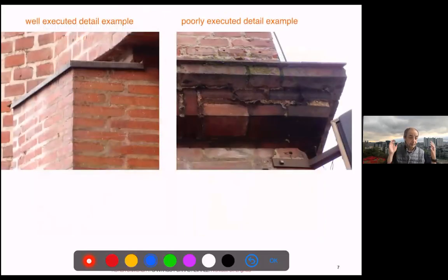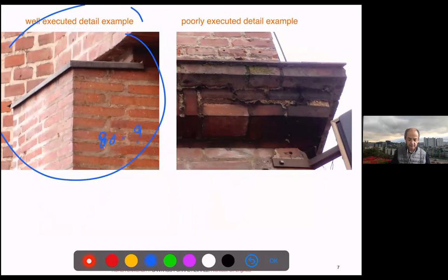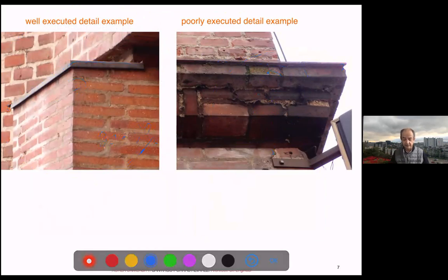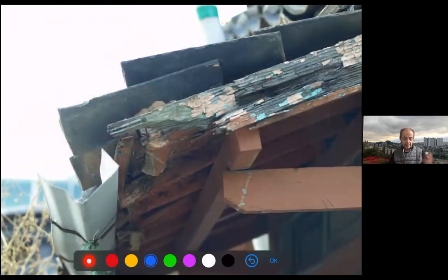And this is a great building. And you see this very well executed. This is almost an 80, 90 year old building. And just a little bit, just 1 or 2 centimeters is enough to have the brick clean. But when you have somewhere in which the water goes through, then the water is washing everything and the brick is ruined. This same building, only here you see the joints were not carefully done, and the water just kept sliding over the bricks. This is here in Korea.